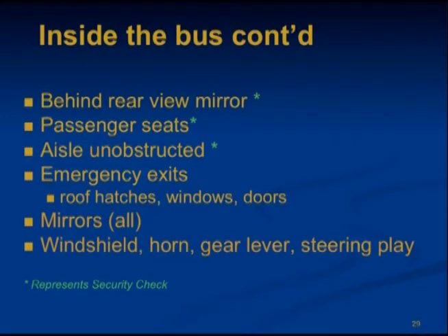Mirrors. It is your responsibility to properly adjust all the mirrors. The flat, convex, crossovers, and rear view interior mirrors should be done according to Federal Motor Vehicle Safety Standards 111. Mirrors must be securely mounted and clean. They can vibrate out of adjustment.